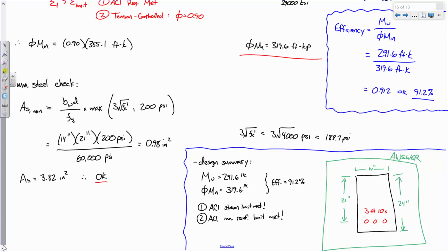On the bottom of the beam, because as I bend the beam, it's in smiley face bending, right? Okay? But that is not the only reinforcement. There will also be stirrups going like that, and they'll be like that, and so on and so forth. How to arrange those and lay those out is something we are going to discuss. That's going to be like a homework 6 type thing. But they will be there because in most situations, the concrete's capacity to carry shear by itself is not enough. So you need that reinforcement.